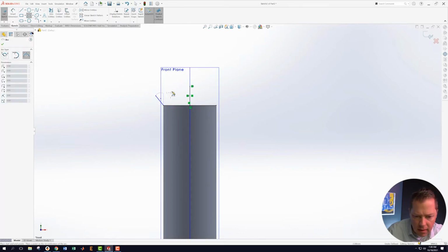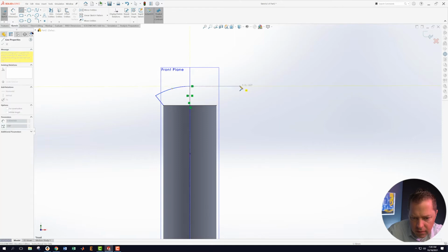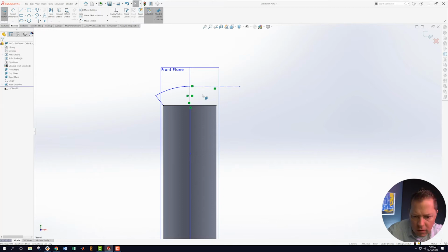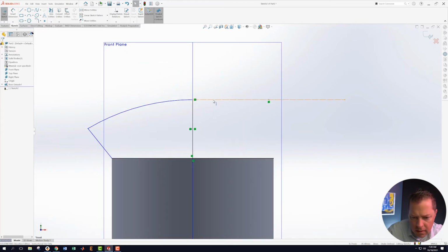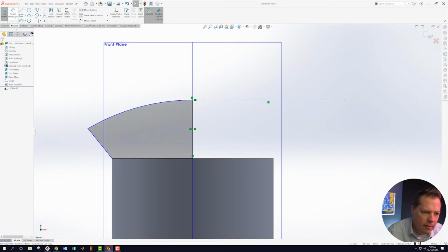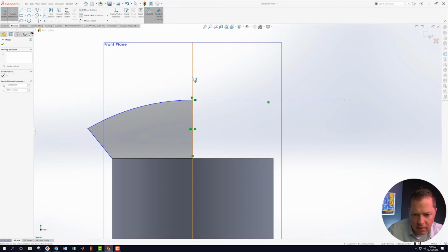And then we're going to get this, and to make ourselves perfectly spherical up at the top, we are going to have to do what we learned in class, which is make this for construction, and then make this and this tangent to each other. Excellent. Now what I need is to trim this because I need to get a closed cross section, and I can see I don't have a closed cross section, but now I do. And now we're going to just dimension this thing out.